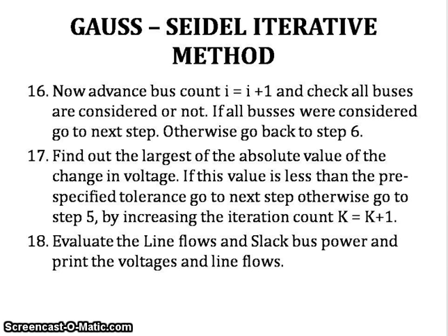By using the latest voltages available for that particular iteration, this will have a speedy convergence. So if you compute with the Gauss method and the Gauss-Seidel method, the possibility of converging within the specified accurate limit is higher in the Gauss-Seidel method than the Gauss method. And also there is the acceleration factor. By using the acceleration factor, we will get Gauss-Seidel convergence in fewer iterations.